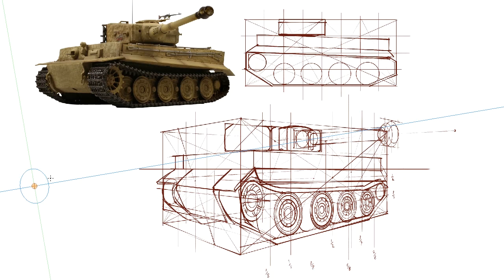But all I did initially was draw an ellipse, draw another ellipse, and then once I get further out, I do need to make sure that my degree changes. So sometimes drawing a box, like you'll see here, I did draw a plane to match this far ellipse here, so that I knew it would be circular and have the correct degree. But here I'm just quickly doing this for demonstration's sake. Having a bunch of ellipses coming out like this can really help you establish a form without ever drawing the cylinders themselves.